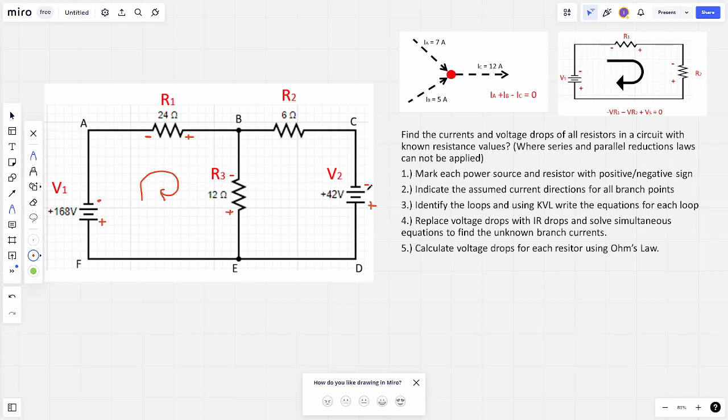Now in this case, negative is here, positive is here. How do we get from negative to positive? We can't jump across the battery, we must follow the loop. In this case, this is counterclockwise. So let's add that in. That's clockwise, that's counterclockwise. So that's negative. The first point of the resistor is negative as we meet it, that's our assumption. Again, as we go down, this is negative, that's positive, and we must go positive back here.